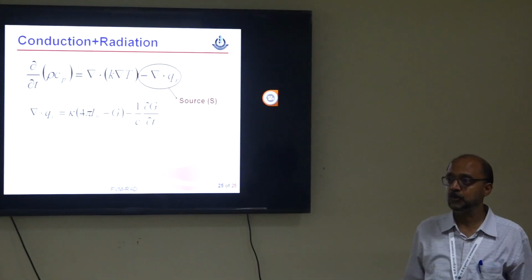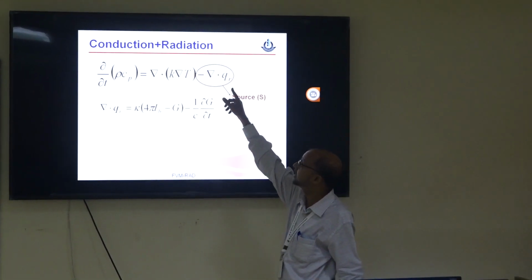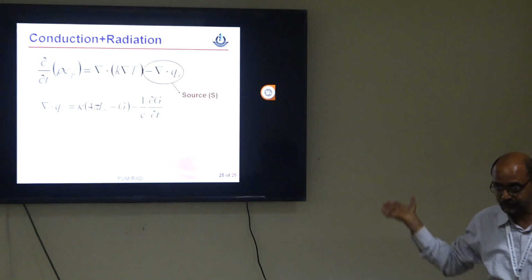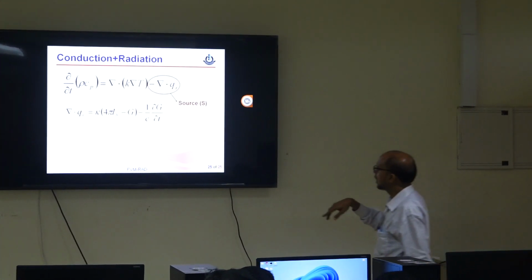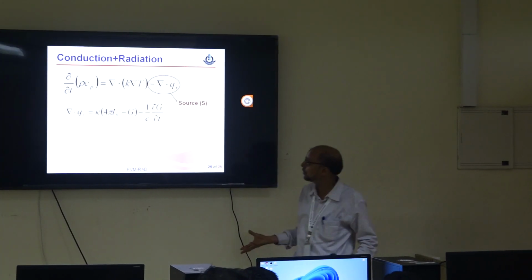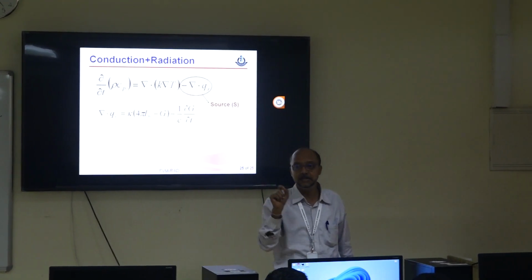Like in your combustion model, when radiation is also included, this part needs to be done. First you have to solve for the RT as we have discussed using the finite volume method. Once your RT is solved, your intensity distribution is known at every location inside the domain. Then the G value is also known spatially everywhere.